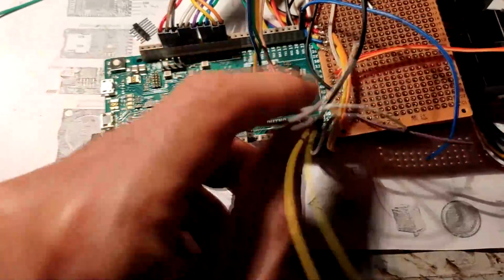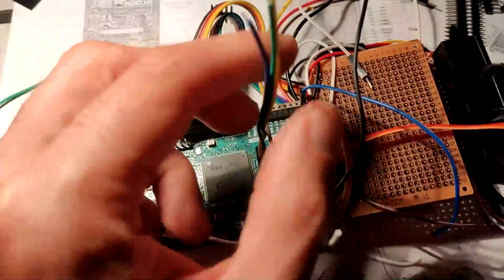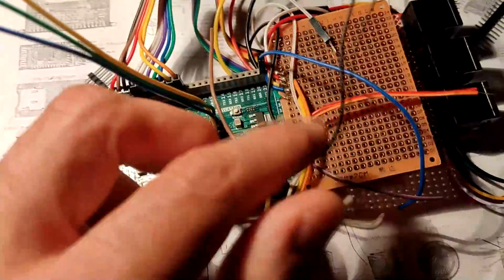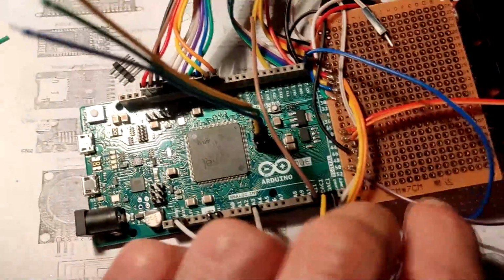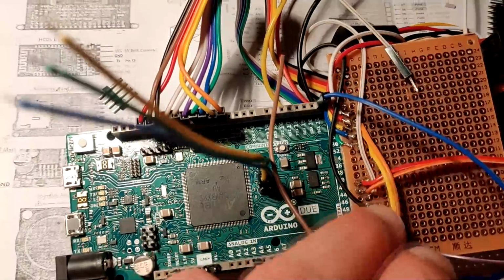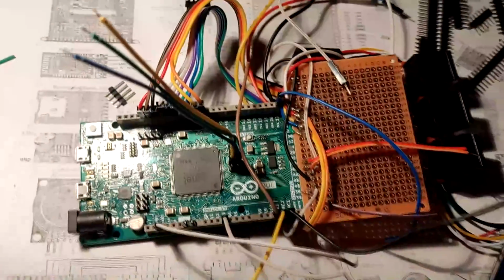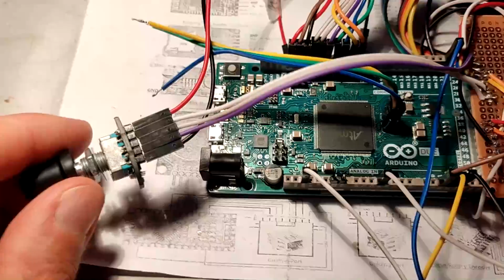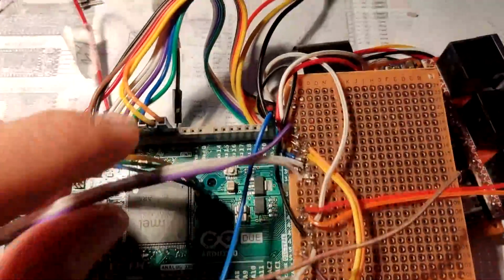So I routed all the cables from the Arduino to the new PCB to have all the pins in straight lines, and I soldered the corresponding wires from the screen, so it will be much better to put it in the box. Here I soldered the 3 wires for the rotary encoder.